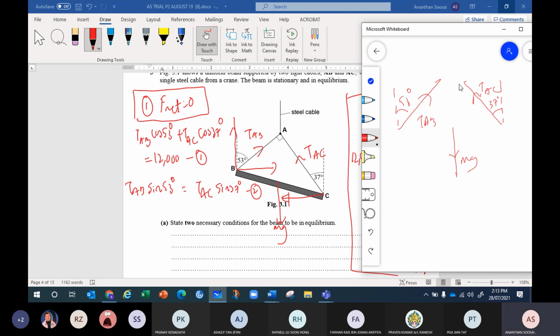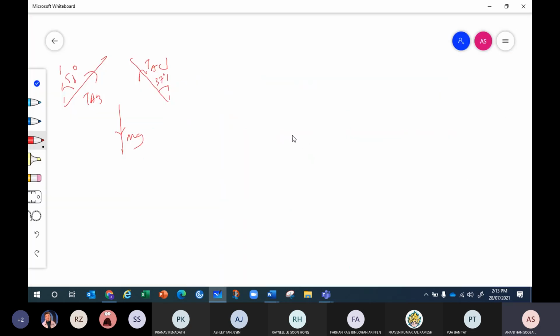Now these three arrows we need to join one after another to make a closed triangle, closed polygon actually. So my advice, first plot out all the vectors with their angles. The angle could be from vertical or from horizontal, from the diagram. Now join one after another to make the triangle. Which one needs to be drawn first? I prefer the one perfectly vertical or perfectly horizontal to be used first. The diagonal connects last.